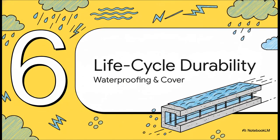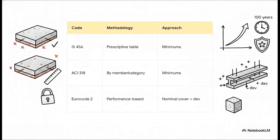And finally, Section 6, Lifecycle Durability and Waterproofing. Let's be real. Concrete cover is your absolute primary armor against corrosion, but how we calculate it varies. The Indian code, IS 456, and the American code, ACI 318, largely rely on prescriptive minimum tables based on exposure classes. The European framework, Eurocode 2, takes a different route. It uses a highly optimized, performance-based approach.